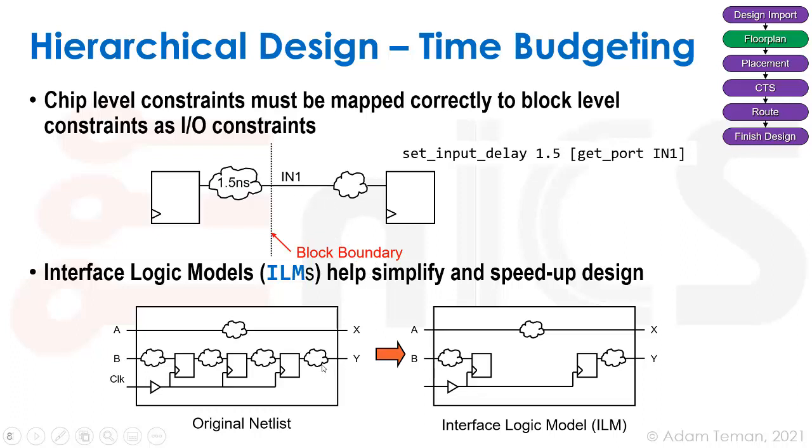What we should do if we have a hierarchical design, where someone else on our team is actually designing the block that's out here, is this. We have the data of what's going on in our input delay, so let's give it to him. He has the data of what he's doing on his output, so let's give it to us and use it for our static timing. The problem is that all of this in the middle is millions and millions, or whatever, hundreds of thousands of gates, and it's going to be a big mess. It's going to be hard to run static timing analysis and take a lot of time and so forth, when it's irrelevant, right?